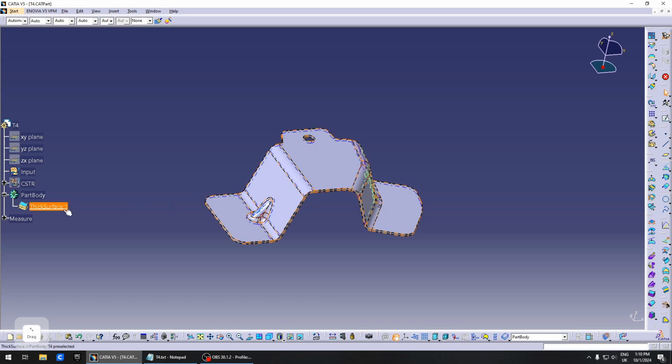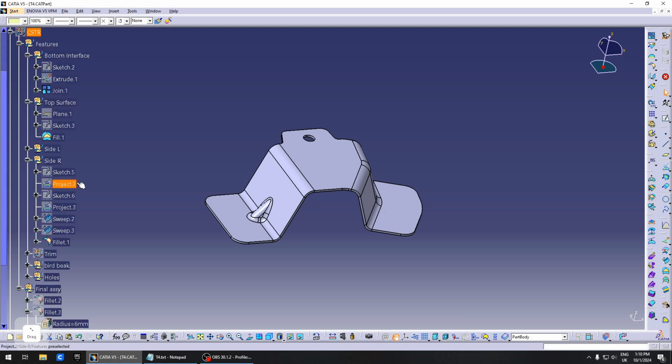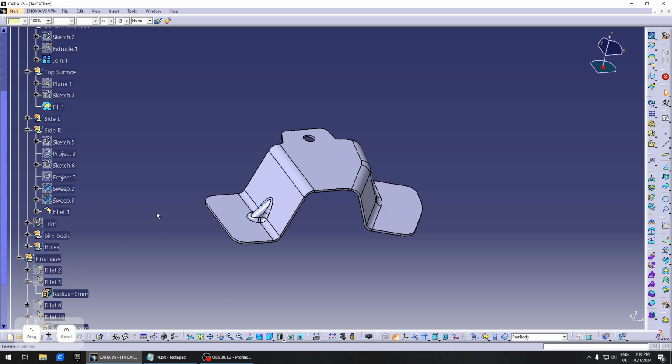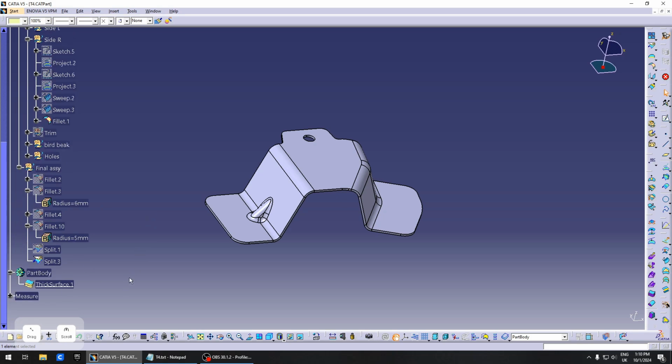Now, we have already covered this in the introduction video, but while working with surfaces, we need to work in geometrical sets. And geometrical sets are a lot messier than body elements due to the fact that they are not ordered, meaning that the order of operations inside the set does not necessarily need to be from top to bottom like it is in solid bodies. Also, elements don't tend to be nested inside other elements like they do in part bodies once you use them.